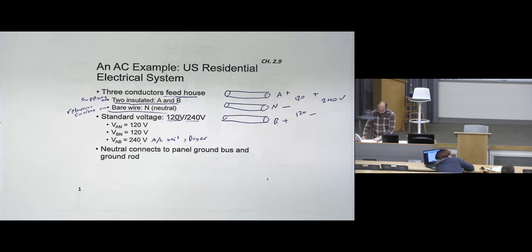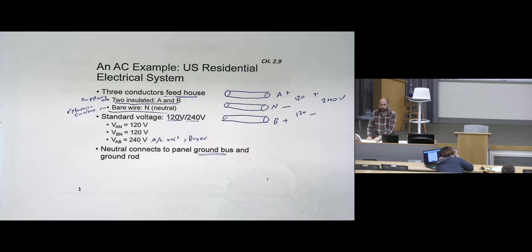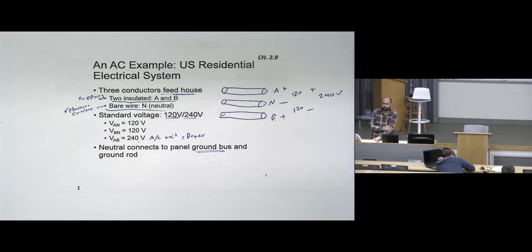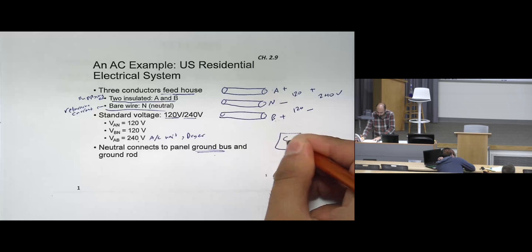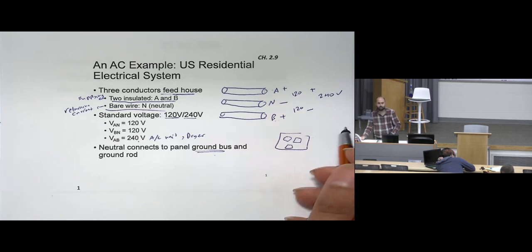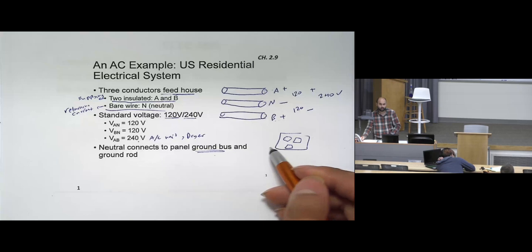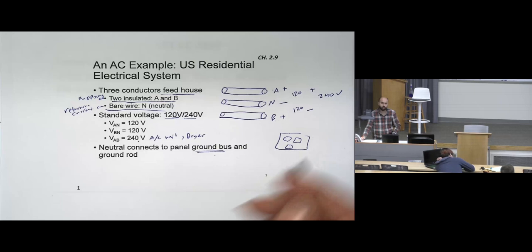There is also a ground bar or ground bus. That ground is used for protection. That's why sometimes when we look at the utility block, we will see 3 spots. Most likely the first 2 are the working spots, one for live and the other for neutral, or phase A or B to neutral, while the third point is for protection, for the ground.